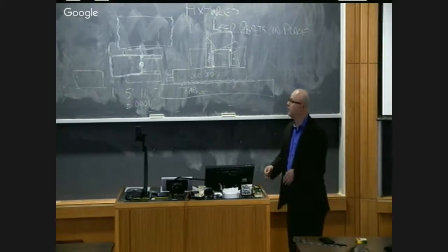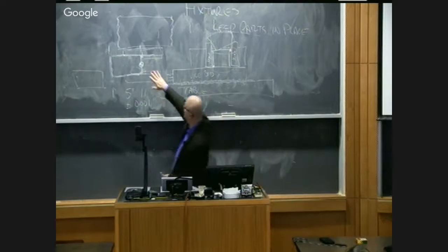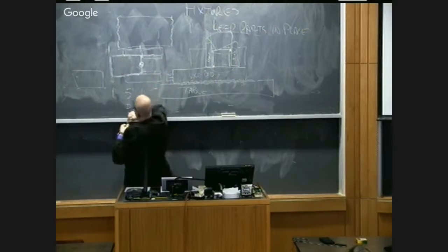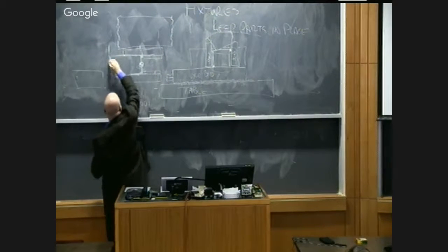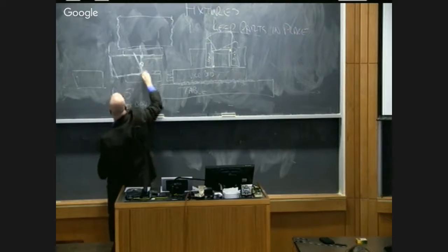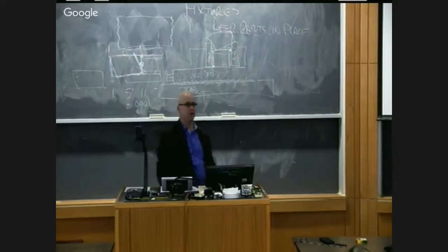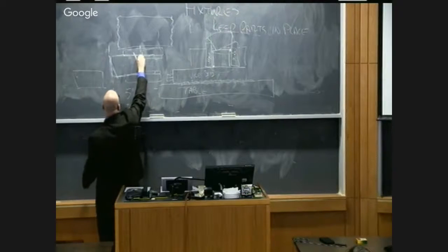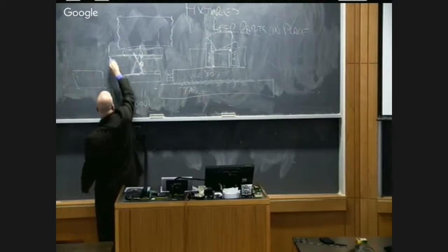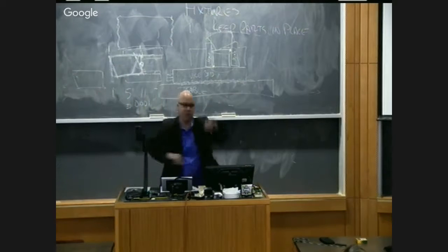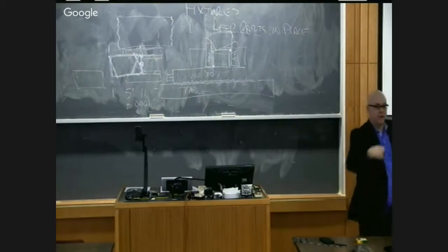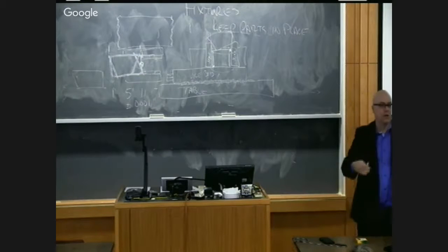That's something we can screw up. The other thing we can do is have this vise twisted on the table like that. And then our finished part would look like this. Unless we flip the part over the other way, in which case it would look like this. So we can make parallelograms or trapezoids all day long when we flip our parts over if the vise is crooked on the table.